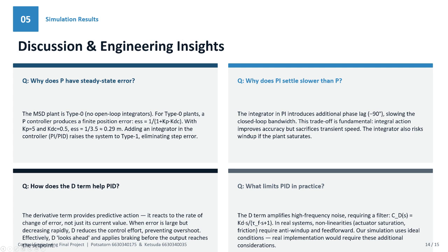Finally, we must consider practical constraints. In a real laboratory or industrial setting, the derivative term can sometimes amplify high-frequency sensor noise. Therefore, our professional recommendation is to use a derivative filter in actual hardware implementation to ensure a smooth control signal.